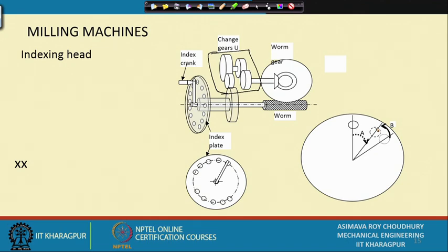And on the milling machine we saw a special type of tool which can be used, which has the conjugate profile of the tooth space. It can remove the tooth spaces one by one. Okay. So, this method is quite versatile, but mind you, for production of accurate gears this method is not applicable. No, this is generally used for maintenance. This is generally used for one off production, one or two of, that means someone gives you an order, you have a small shop and someone gives you an order, I want 5 pieces of these gears, then you make it for him.